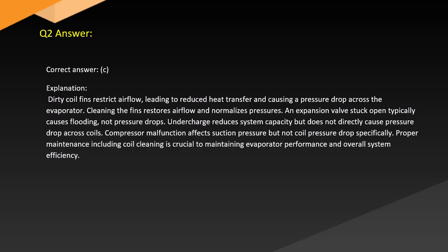Answer. Correct answer: C. Explanation. Dirty coil fins restrict airflow, leading to reduced heat transfer and causing a pressure drop across the evaporator. Cleaning the fins restores airflow and normalizes pressures.